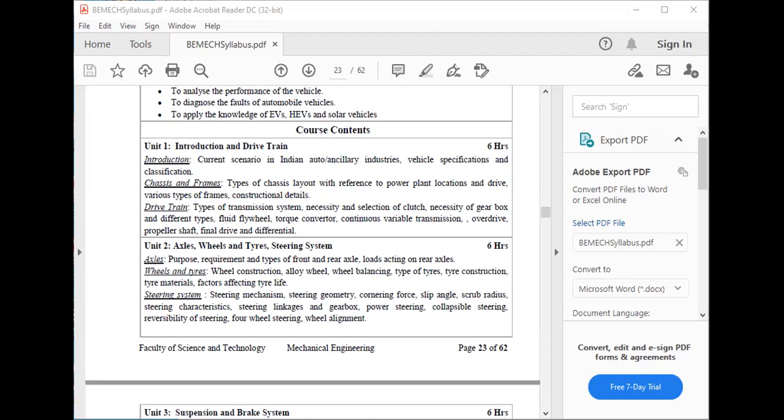Then the clutch release bearing is available there. It transmits the movement of the clutch linkage to the pressure plate. It is usually a ball or roller type of bearing, and it is self-centering to compensate for clutch alignment variances. So this is the ball bearing, as balls are provided, and hubs are provided, and the outer bearing shell is there. This is the release bearing, also called the throwout bearing.